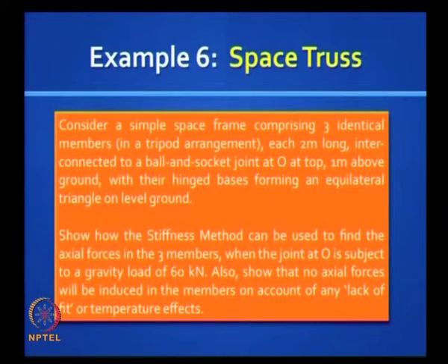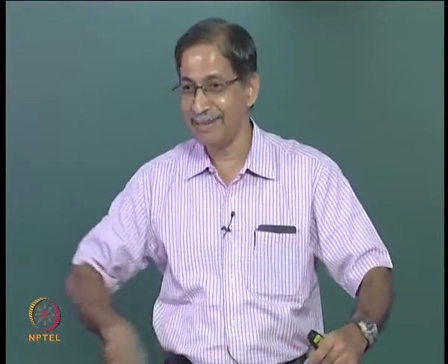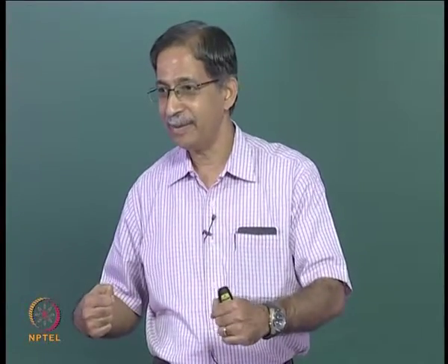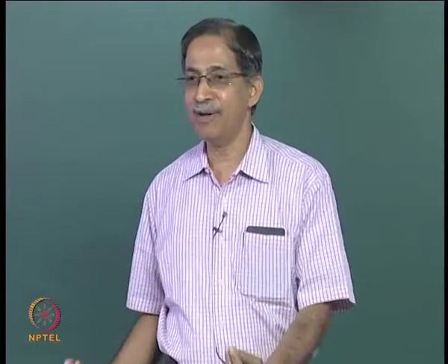Now I have seen you people put some triangle there so that it does not move in the corners, when you use the theodolite. That is as good as providing a hinged base, otherwise you have to plant it firmly on the ground so that it does not move.